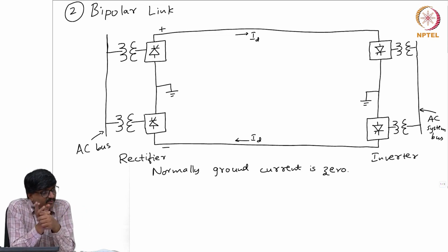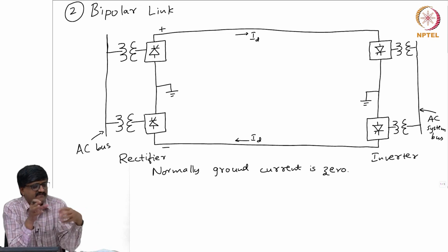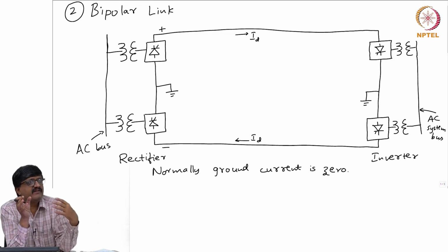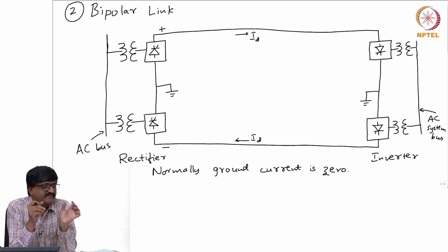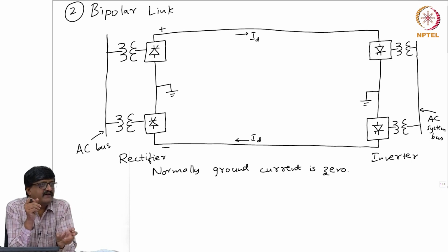Now, when it comes to one more transformer, there is Y delta. What I do here is assume that the Y delta transformer can also be represented by the same inductive reactance corresponding to leakage, and another set of voltages. The only thing is, the two voltages are identical except for what? Phase shift, that is all. So, one assumption made here is that the equivalent leakage inductance for both the YY and Y delta transformer is the same. That is the assumption.